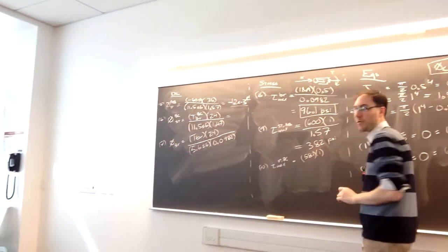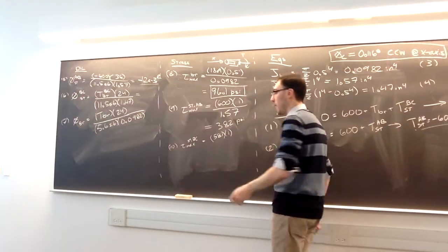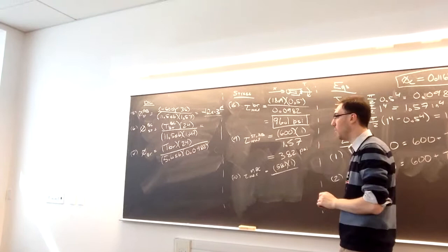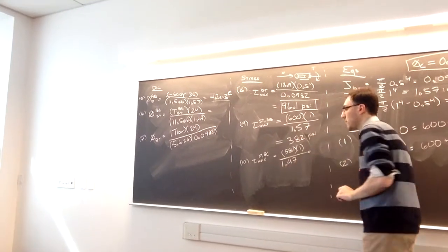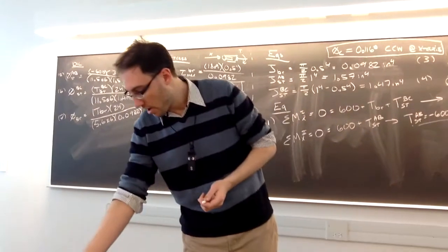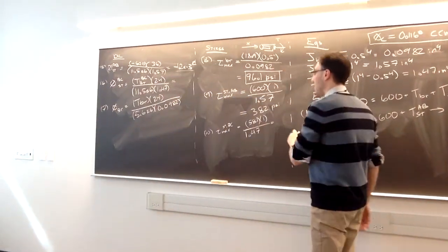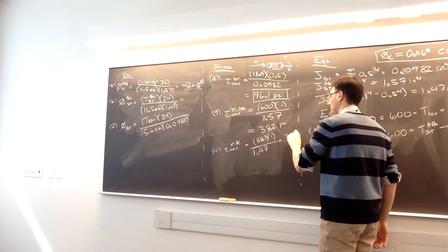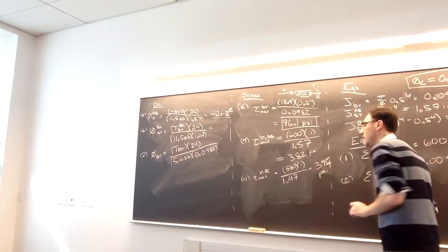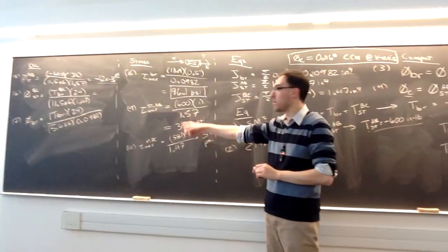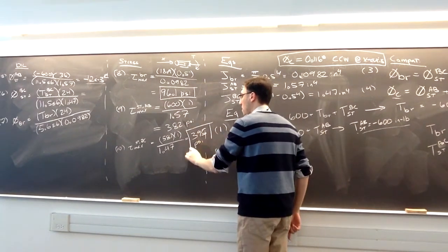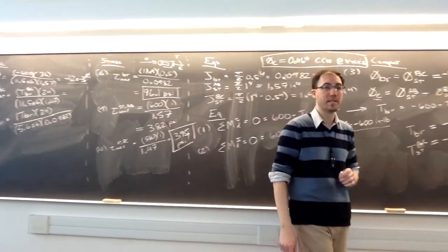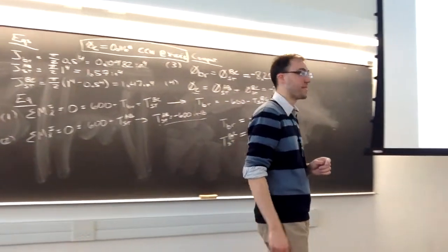Sorry, this section is the hollow one, but the outside radius is still 1. But its value of J is also a little bit smaller. So the shear stress will be different here. Here we actually get 395. So even though the internal torsion is lower, because that J also declined, we actually get a higher shear stress in section BC of the steel than we get in AB of the steel.